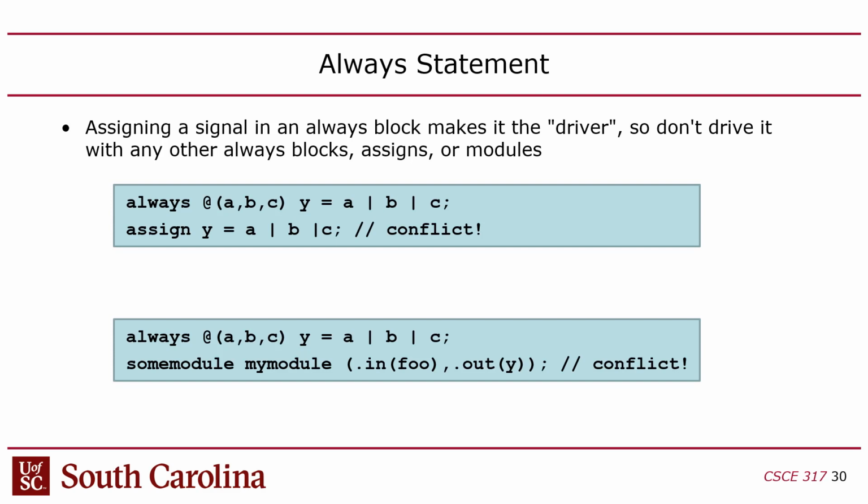This is a structural line of code because I instantiate another module, but these first 3 are behavioral because always and assign are our behavioral idioms. Behavioral meaning it actually does something other than just creates a schematic. Remember that a lot of Verilog code is just schematics. All this structural stuff is just, I want to create this and connect it to that. That's just schematics, right? The behavior is when you actually have it do something, like create Boolean logic of some kind.